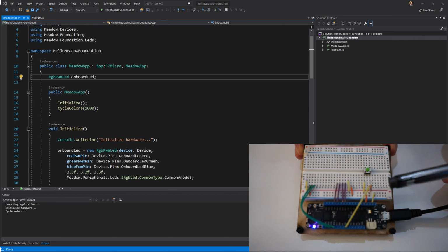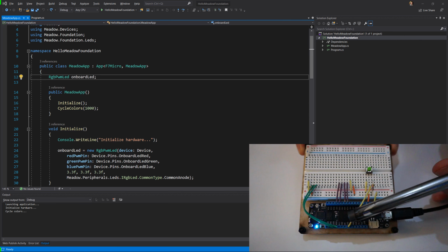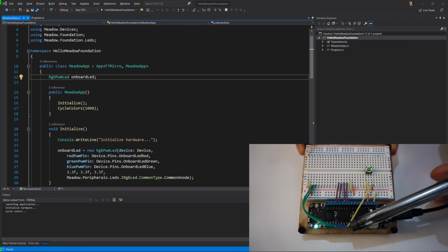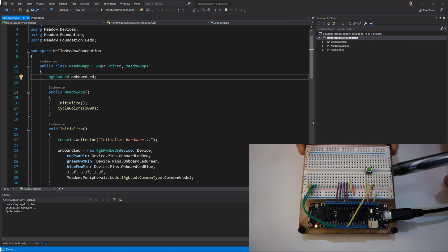And so what that means is that in the default state, this whole jumper wire is set to ground. And so we're actually pulling this pin down to ground, and that's pin D12. Now over here, when we push the button, it's actually going to connect across the points. And what's that connected to? Well, this jumper here is actually connected to the power, so that's going to raise this up to 3.3 volts. And the reason we have the resistor here is so we don't short out power through ground. So this kind of slows the current.